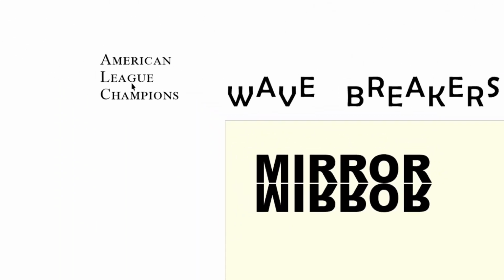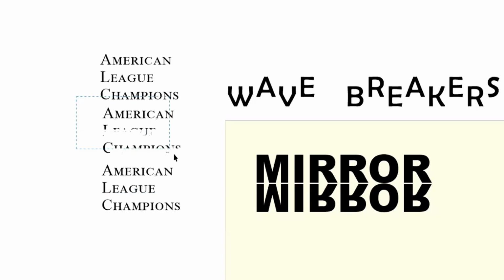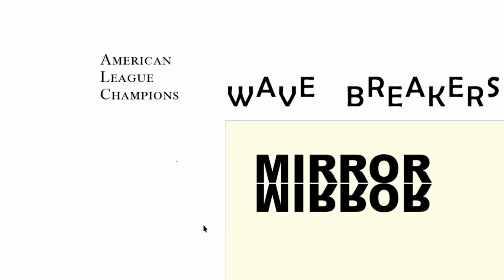Again, let's say I had this object over here, and I click and drag down and right click. I click and drag down and right click. So basically, just using the right click after you drag something down, as long as you don't release the left mouse button, it'll make a duplicate of it.